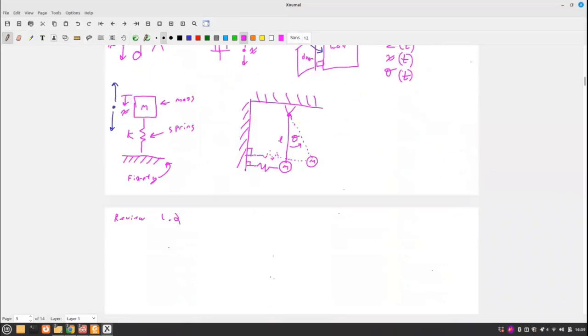The assumption of small displacement states that the displacement of a system is considered smaller than the initial geometry of the system, right? That means second order effects caused by the displacements within the system are ignored. The second order effects could be loads or angles at the points of linkages, springs, connections, right? So that's the assumption of small displacements.